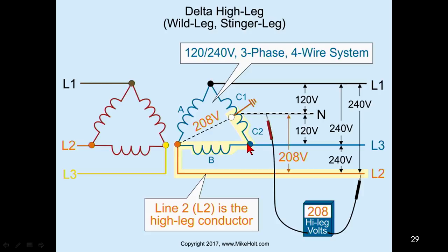Now, years ago, you could get 3 separate transformers. This could be 15 kVA, this could be 15 kVA, and this could be 50 kVA. But if you're going to get a 3-phase transformer that's already constructed as an assembly, then your line-to-neutral loads are limited simply because they can only be installed on one phase. And like you're saying, years ago it was 5%. Now they're saying they've done something to allow it to be 30%.